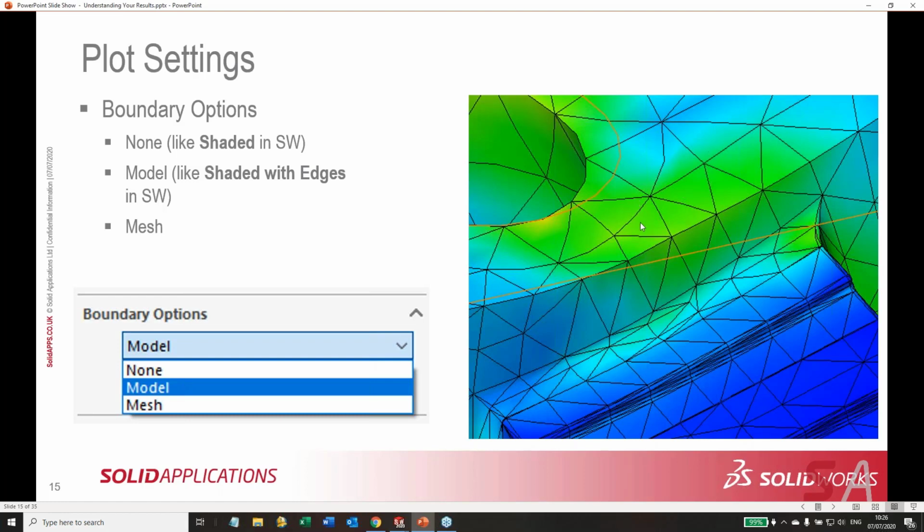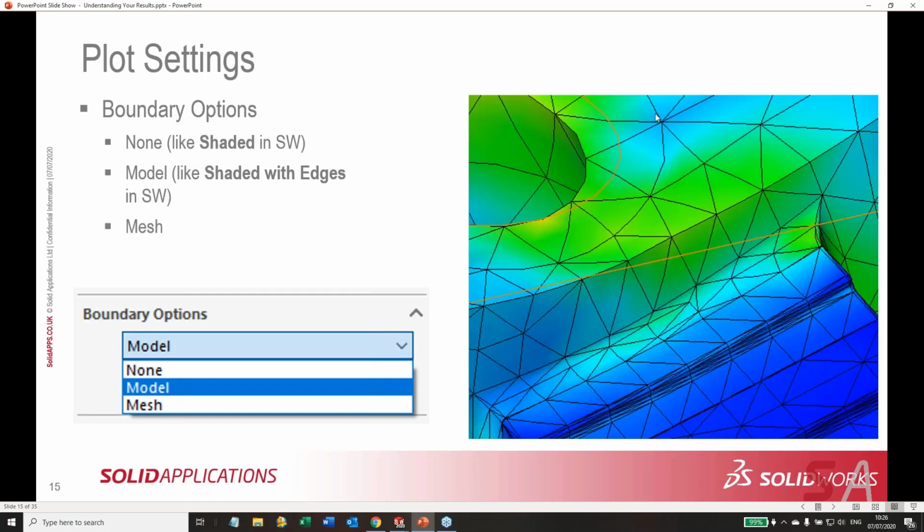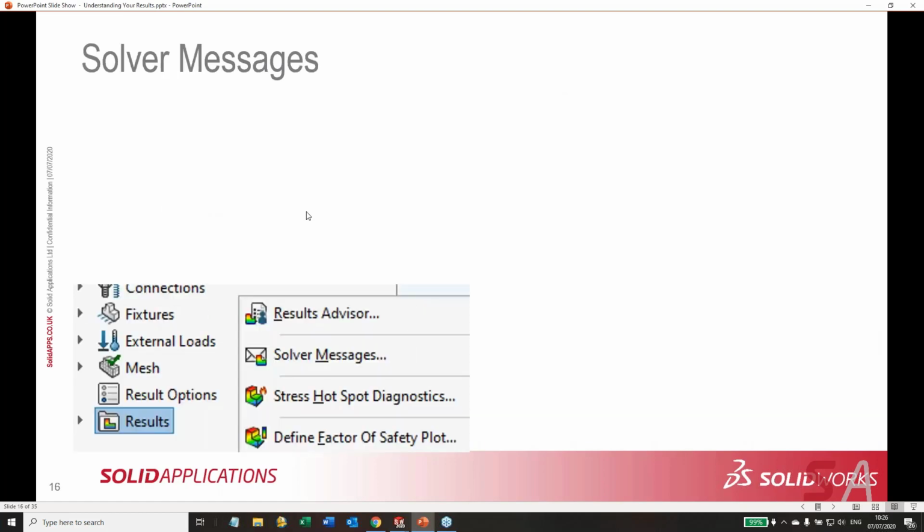That's useful if you're getting some of that triangulation in your stress results. If we look right up here, you can see little bits of stripiness or triangular shapes. That is an indication, if that were a high stress region or a rapidly changing stress region, that I might want a finer mesh there. When you see the triangulation there, and then you put the mesh over the top of it, you can see that it's going along a mesh boundary, okay? You know you have a node here and a node here and a high quality mesh, so you almost have a 3-node triangle here that you see with this blue region. So the mesh will give you good information.